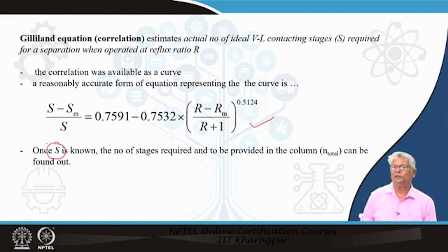From this we know we will be subtracting and adding 1 for different reasons, for the reboiler, condenser, partial condenser, taking credit for the feed tray or not, and we definitely will be knowing the number of trays required in total for the desired separation within the column itself.